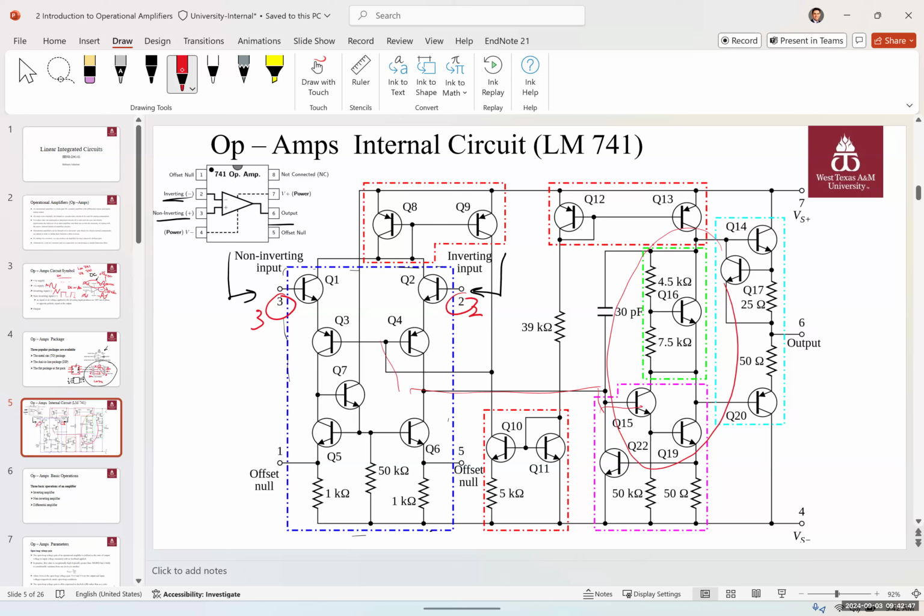A Darlington pair in electronics, if you have had Electronics 2, is an amplifier that multiplies the gain of each stage of amplifier. So it's a boosting amplifier, I could say. And through some amplifiers, it goes to the output. So we have multiple stages of amplifiers. That's the reason we have a huge amount of gain in an operational amplifier.